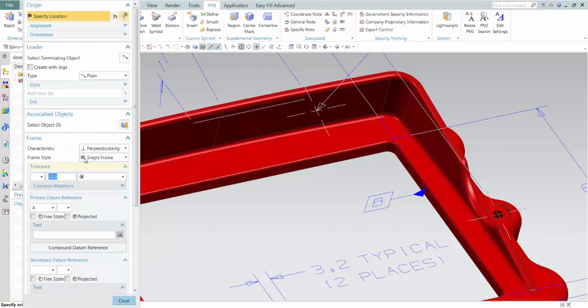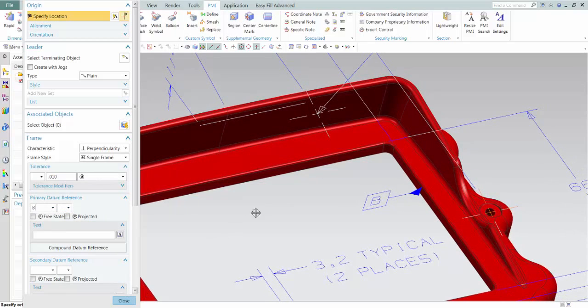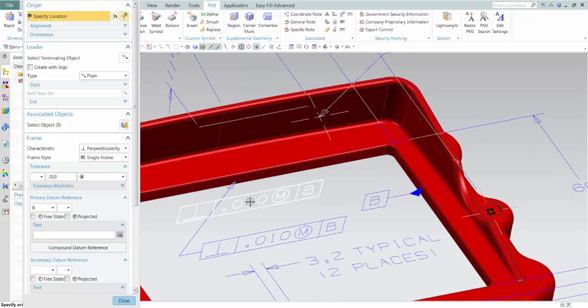and then as well I may want to do a feature control frame, and you have all the different types of feature control frame information you may want here, from flatness to perpendicularity, angularity, all those things. We're using perpendicularity in this point. You can key in whatever values you want. You want maximum material conditions, what datum are we interested in here? We'll make this B, of course, to match up to that. And all we have to do is just tag on a face, drag to a location, and we've got those placed out here as well.